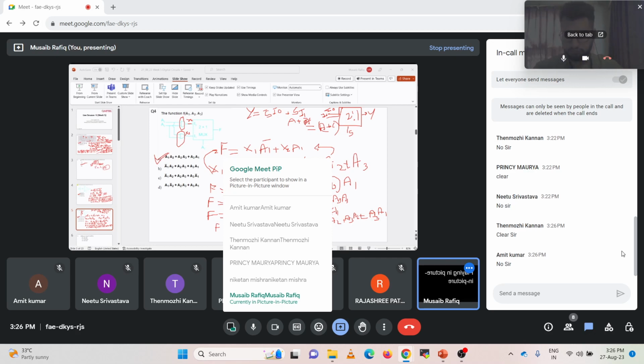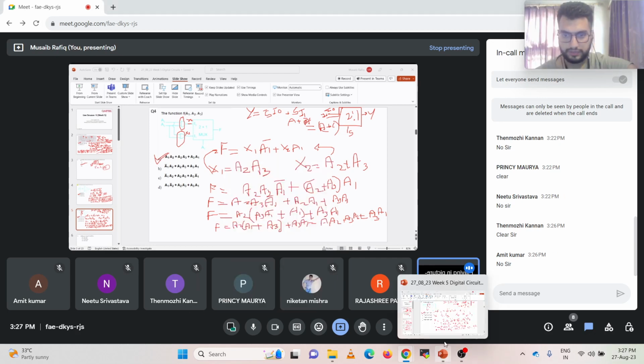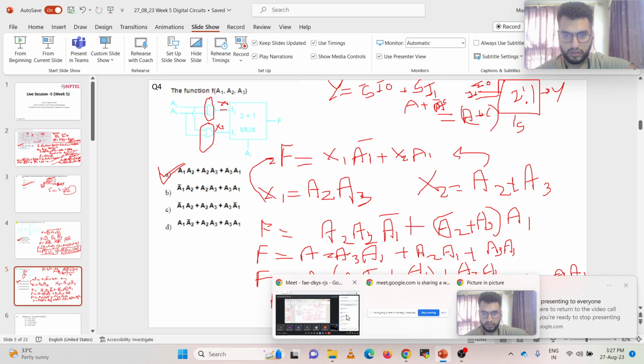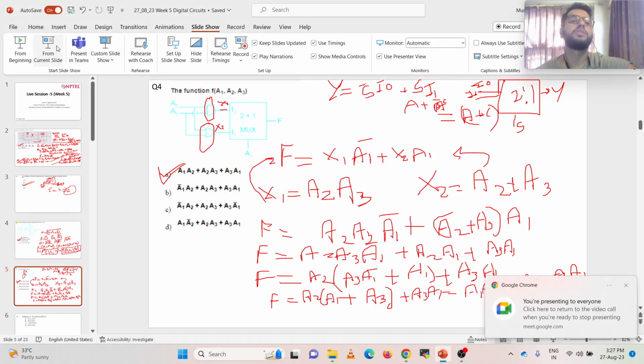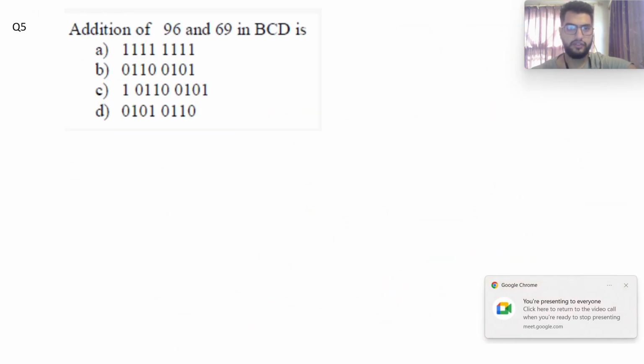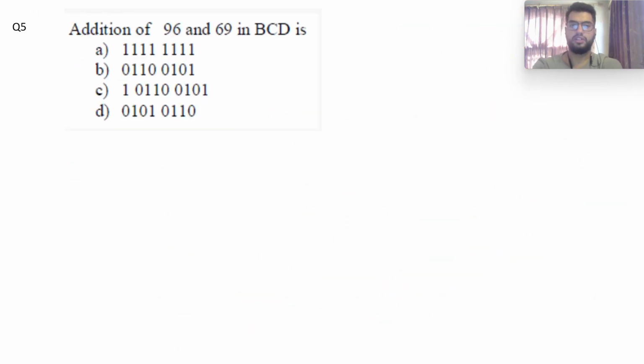So that's nice. Now let's move forward to question number 5 of today's live session. It states that addition of 96 and 69 in BCD is, so we have two decimal numbers 96 and 69, and we need to find their addition in BCD, that is binary coded decimal or 8421 encoding.